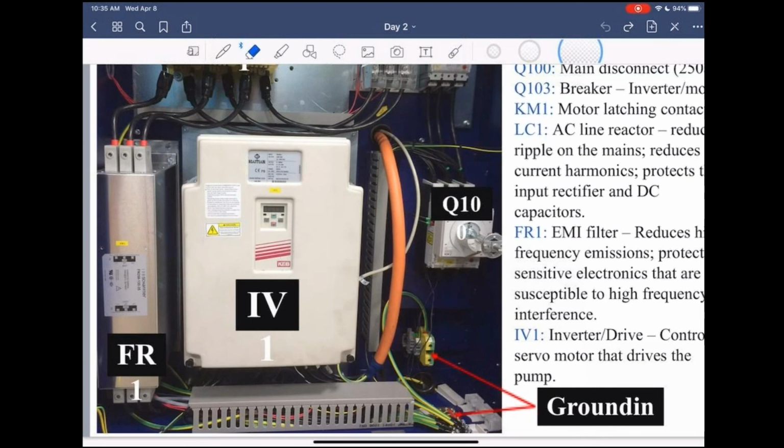So if your grounding strap has a lot of noise on it, then your 0 voltage reference for your KEB inverter will not have the proper 0 voltage. Therefore, it'll react differently. You'll have different pressure spikes, and things won't maintain a good process.